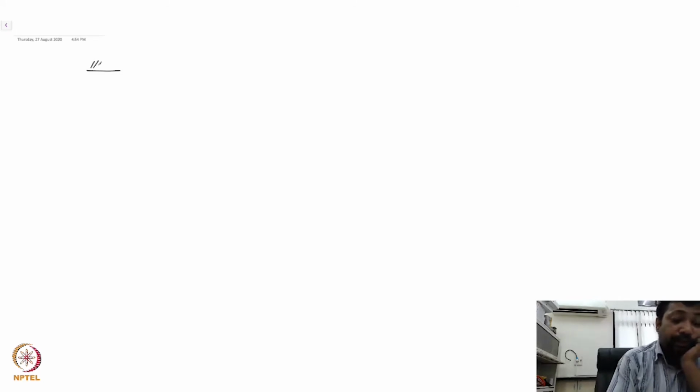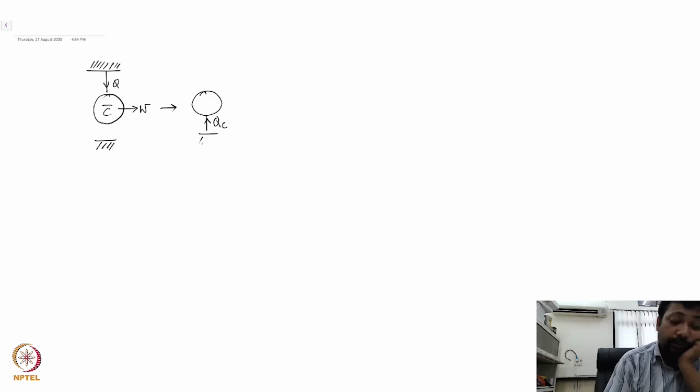The other way around is when you violate Kelvin's statement. So let's violate Kelvin's statement on purpose. So I have a machine, which I denote by a bar because again it's violating a statement. It draws an amount of heat Q from the hot reservoir and does an amount of work W, completely converting this heat into W. So this violates Kelvin's statement. Now this work I can use to drive a refrigerator. A refrigerator would take up a heat QC and would dump a heat QH.